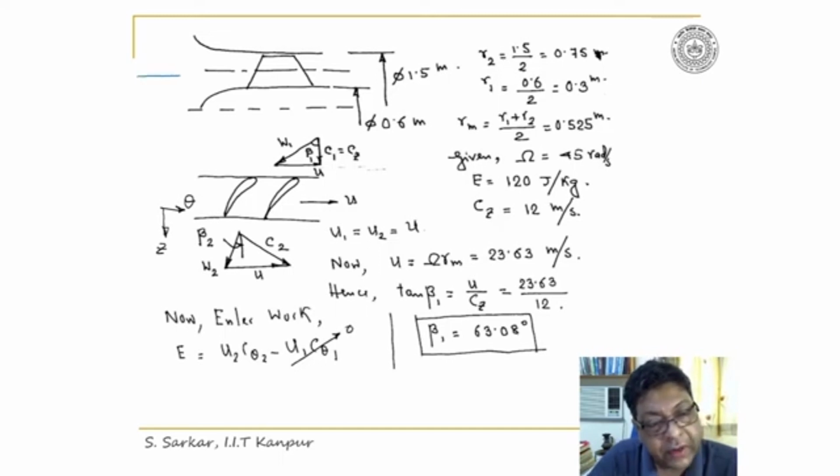I have drawn here the schematic of the axial flow pump where the hub, casing, and impeller have been indicated. Furthermore, I have shown here the axis of rotation and a central plane which lies between the hub and the casing. The radius of the central plane is considered here as Rm.